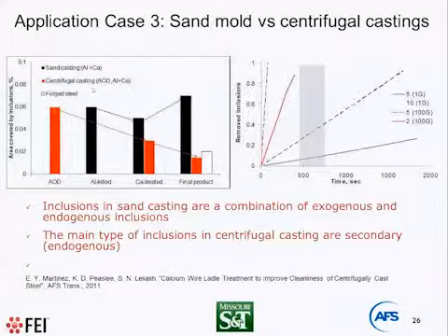Interestingly, centrifugal casting technology provides a completely different trend. We have decreased inclusions because we have huge centrifugal forces. And this is the right picture to show what's going on. When we have simple 1G gravity, we have buoyancy-driven flow, and this is the calculated flotation time for inclusions of 5 microns or 10 microns. We can see that to float an inclusion we need a minute, an hour, which is not possible in our foundry business, and all these inclusions stay in the melt.